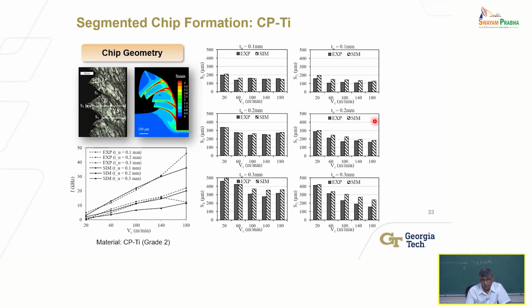That's a tough question to answer because, for example, in titanium, it is a function of the process mechanics. In other words, it's a function of the behavior of the material, right? This material is a low thermal diffusivity material, which means that it cannot conduct the heat away fast enough. So heat accumulates in a narrow region, and the material softens significantly. That is one theory, right?